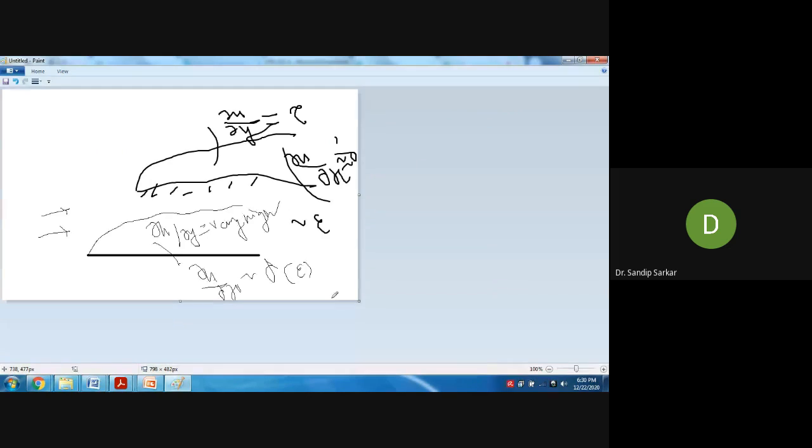You have done this order of magnitude analysis in the boundary layer equation, yes. So del U del Y is not 0. It will be very high because it is basically a manifestation of shear stress. Shear stress is limited within this boundary layer, where it is a function of del U del Y only. Clear? That's why del U del Y is not 0.